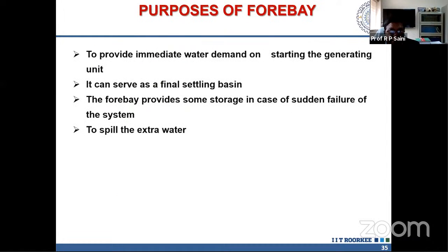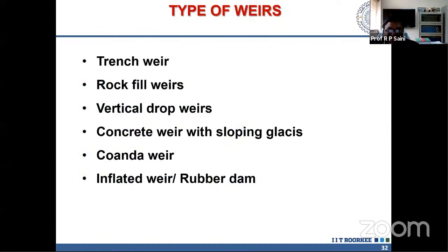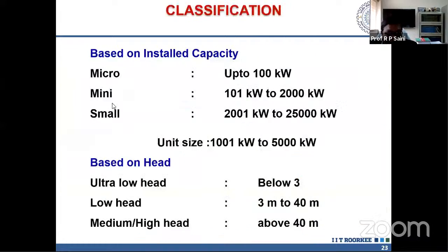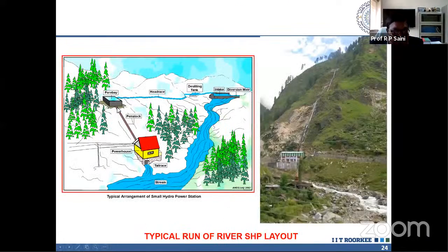Then I think this is the forebay tank. This is also a very important component. I'm just quickly telling you that this is the forebay tank. This forebay tank is basically used to connect this circular pipe to this rectangular channel. That's one function.